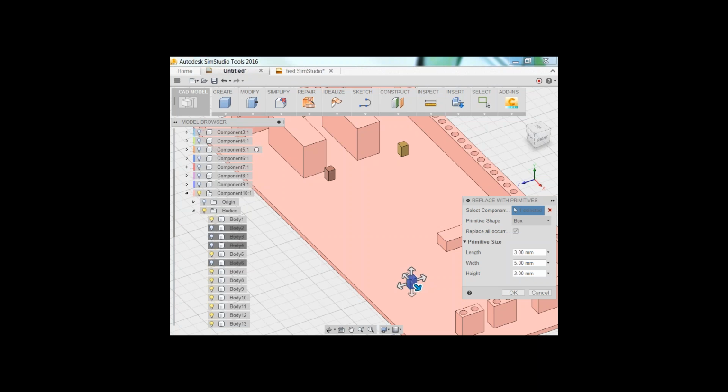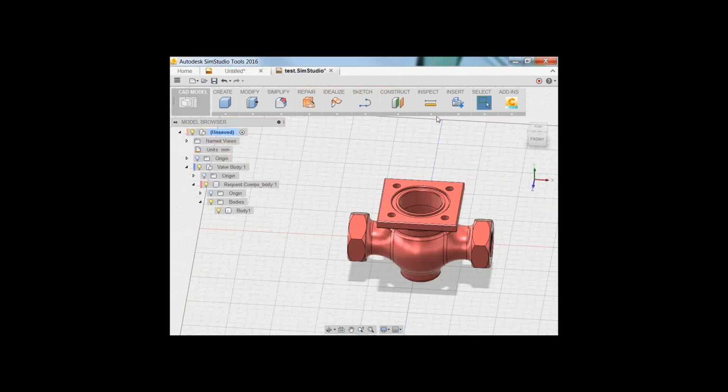Mike, that's definitely a question more for when I get into talking about the meshing line, but I'll try and give you a fairly basic answer now. You can create volumes that are extra air that we can modify the mesh specifically on that region, and the regions that are available in CFD, they're limited to what the shape can be, and the control on them isn't quite as nice as if you create them using CAD.